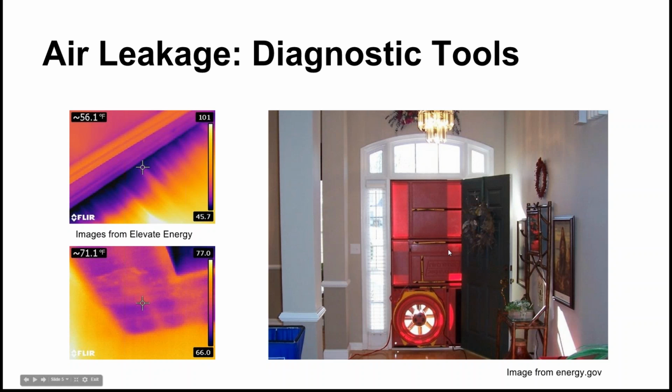So this blower door test can tell you a lot about what's going on in the building with respect to air leakage. Qualitatively, once you have depressurized the home, you can move around and look and see exactly what's going on. You can actually feel air moving in through leaks, like around windows, in the baseboards, by the attic, all sorts of things. But then quantitatively, you can also measure air volume out through the fan.